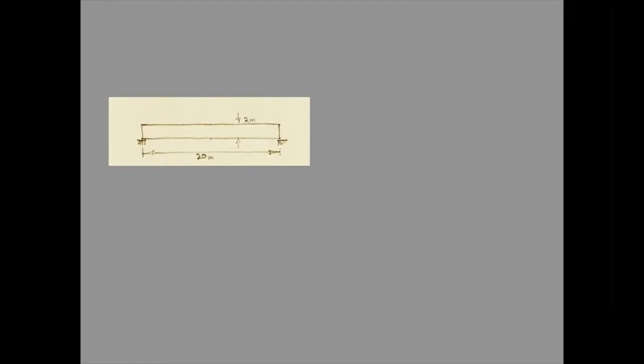Another example of the effect of form on internal force, and therefore efficiency, is given here. This is a reinforced concrete beam that spans 20 meters. Under typical loading, a depth of around 2 meters would be required to give it adequate strength. This would limit the stress in the material to an acceptable level.